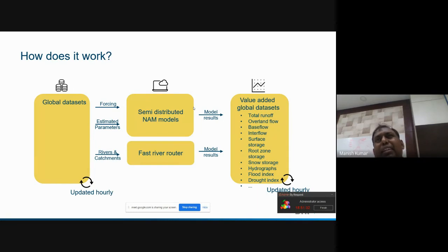And the quality of the rainfall runoff model is around R square of 0.6, with water balance within plus or minus 5%. In some regions we are getting very good results, but there are certain problems in some other areas, and the average is 0.6 R square. We are still working on that, and we expect the results will improve in our next release.